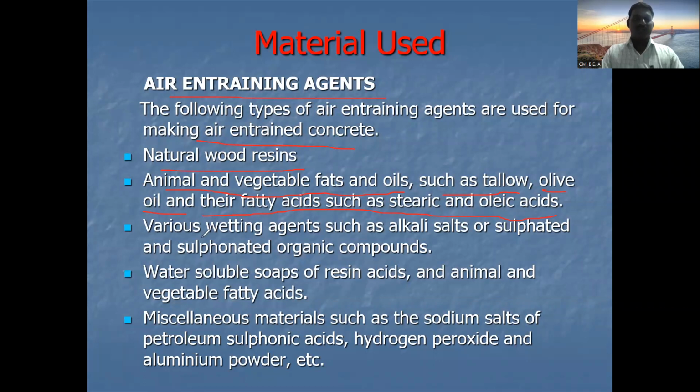and increase the workability of the concrete. Again, the various wetting agents such as alkali salts or sulfate and sulfonated organic compounds are also used. So these chemicals we are adding into the concrete. So this is the need to increase the air content in the concrete.